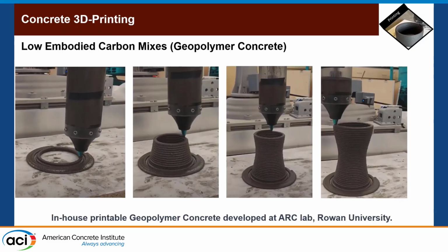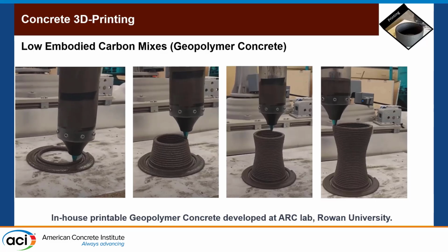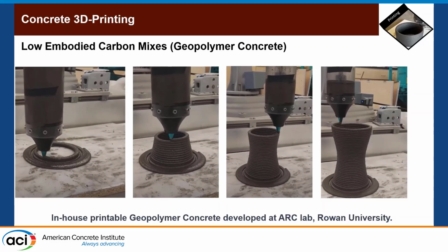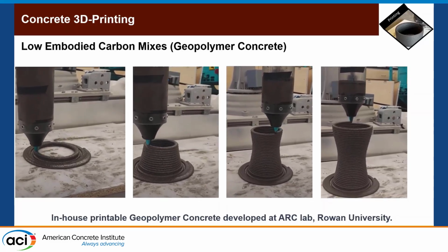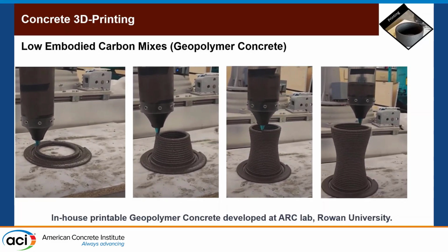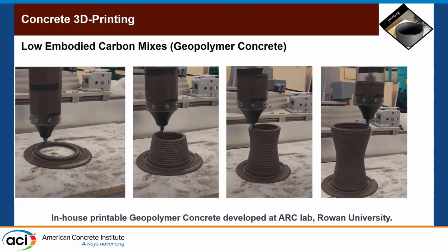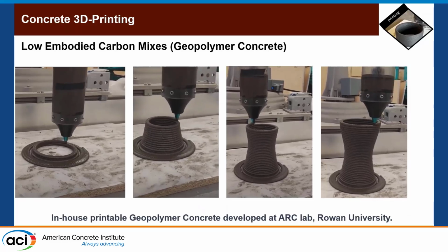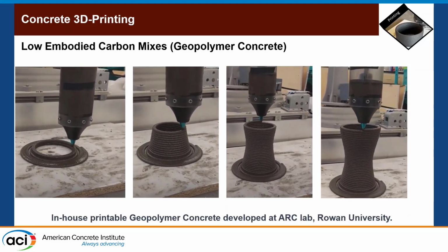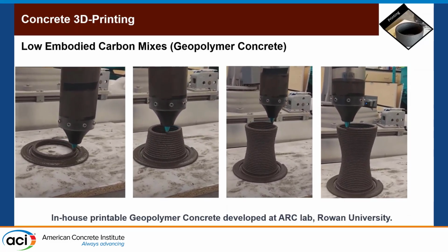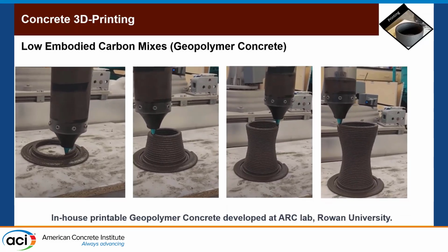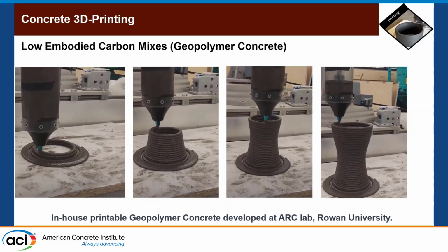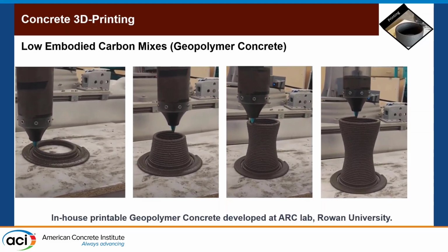This is another project that we work on with geopolymer concrete. This is Ali's work, and he is working to optimize a cementless material. So we are not using any cement, and this is a geopolymer, and we have a lot of additives that we add to make it printable. We ran into a lot of difficulties with this material. It sets very fast, within 10 minutes, and we actually shattered a couple of tubes in this process.